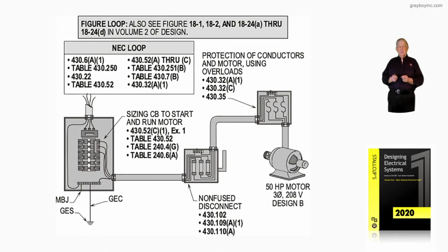Now this illustration deals with when an overcurrent device can be sized greater than the ampacity of a conductor or the full load current rating of a motor. Now, many times where a problem occurs is when, say, you had a number 10 conductor feeding a motor or an air conditioner, and the overcurrent device is greater than 30 amps.